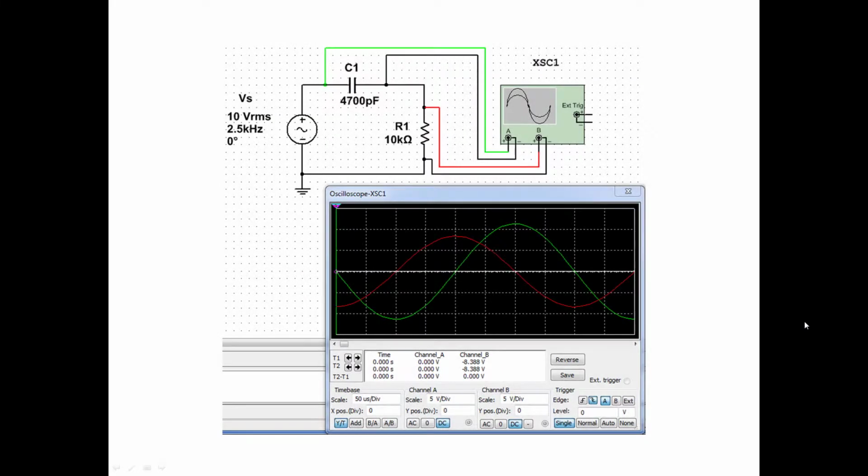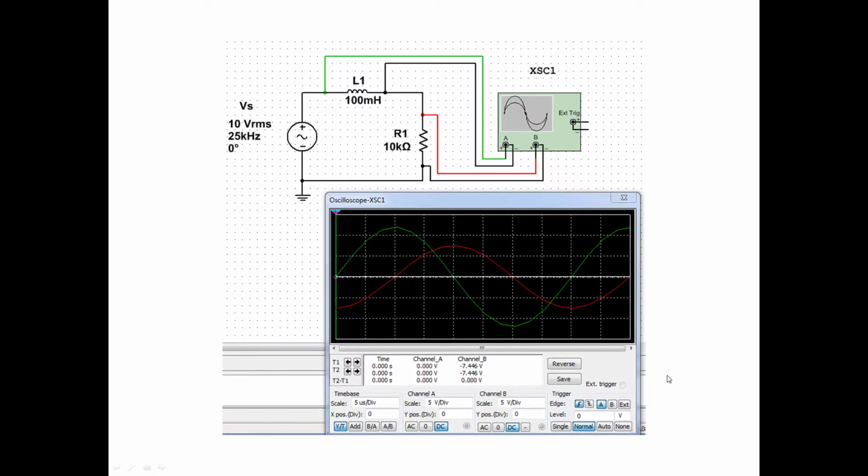Good day. Reactive circuits are circuits that contain reactive elements like capacitors and inductors. Reactive elements are components that shift the phase relationship between the incoming source voltage and source current that feed the circuit. Some components shift the phase to where the source current leads (happens before) the source voltage in time: capacitors, while other components shift the phase to where the source current lags (happens after) the source voltage in time: inductors.